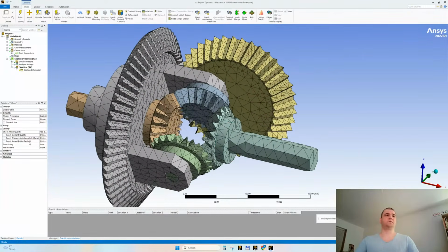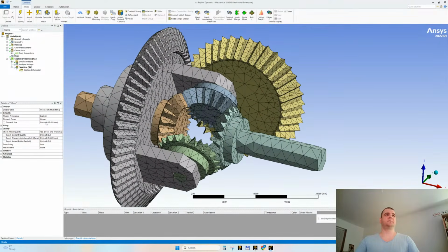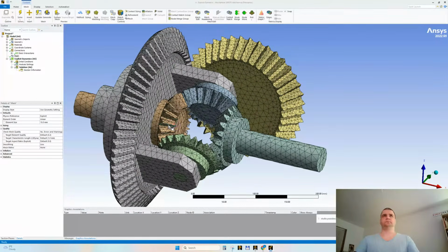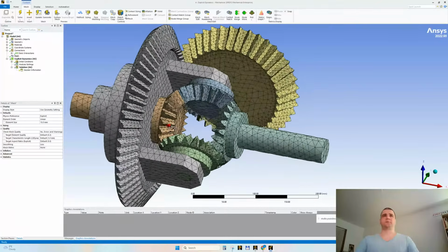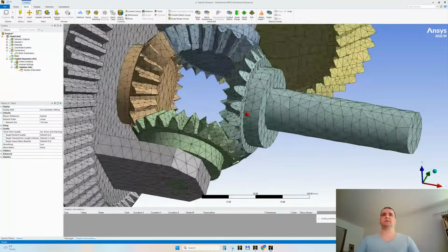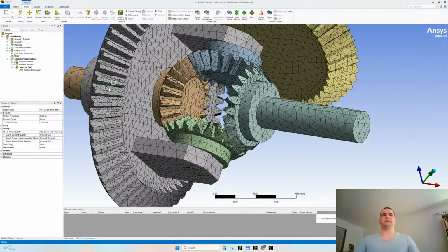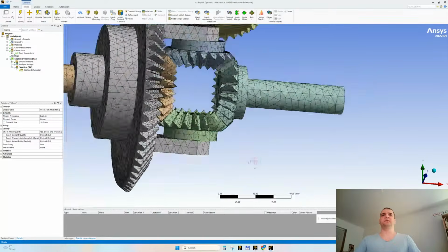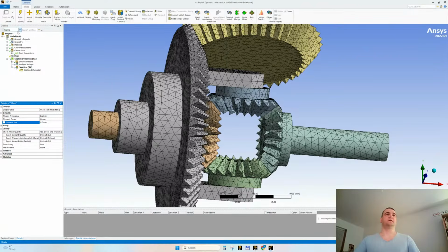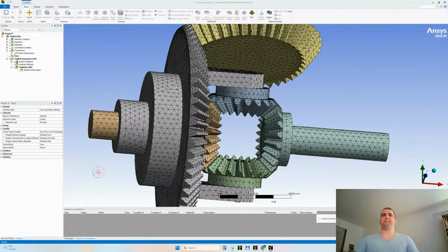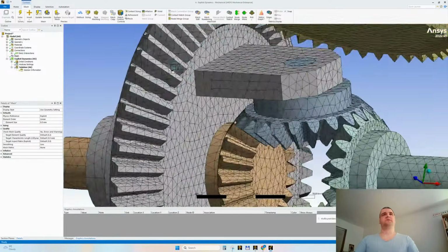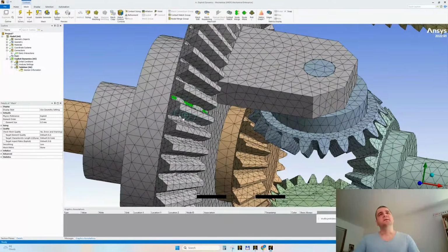Yes, it's pretty coarse to say the least. Let's see the default sizing, 18 millimeters. Should we make it, I don't know, maybe 10? Right click, generate mesh. We can stay with such a mesh because it's explicit. In static and transient we have no excuse and we'll get lots of errors. Yeah. Let's change instead of 10, let's maybe make it 8, and we will refine some faces manually. So I would say this is kind of, even though the, oh my God, it's,